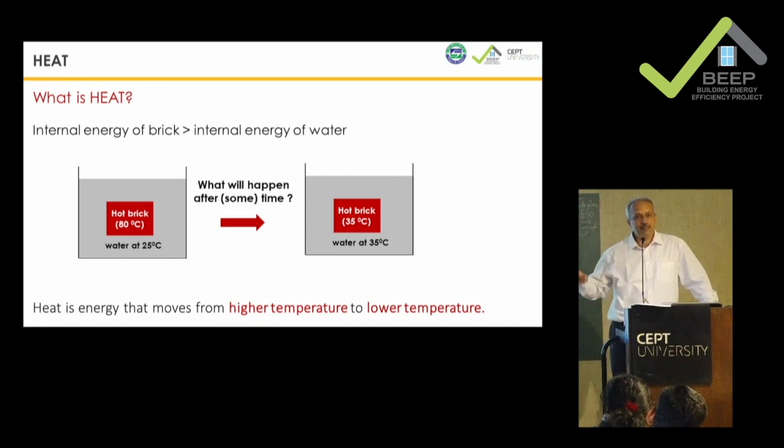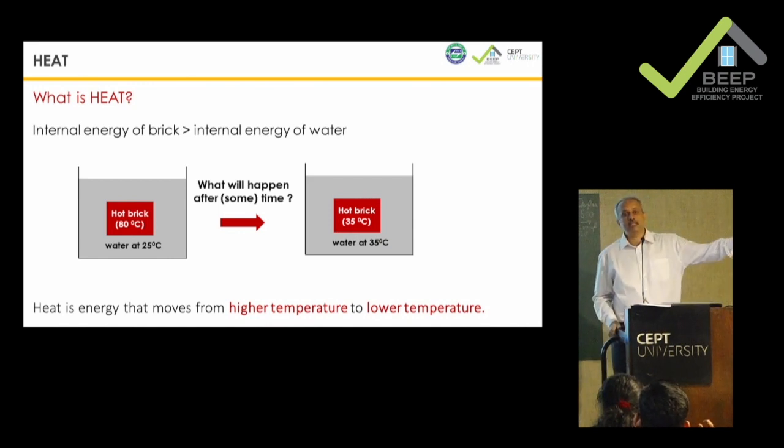Versus a basement of a Jaisalmer Haveli, where you do not have any windows or means to change the air. If the outdoor temperature, this is the basement, so the outside soil temperature, let's say goes up to about 32 degrees and inside is 25 degrees, how long will it take for this 25 degrees to go up to 32 degrees? Why am I saying 32 degrees?